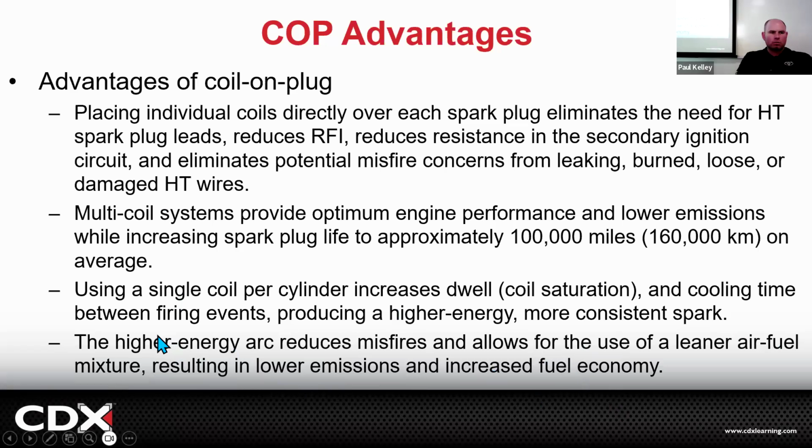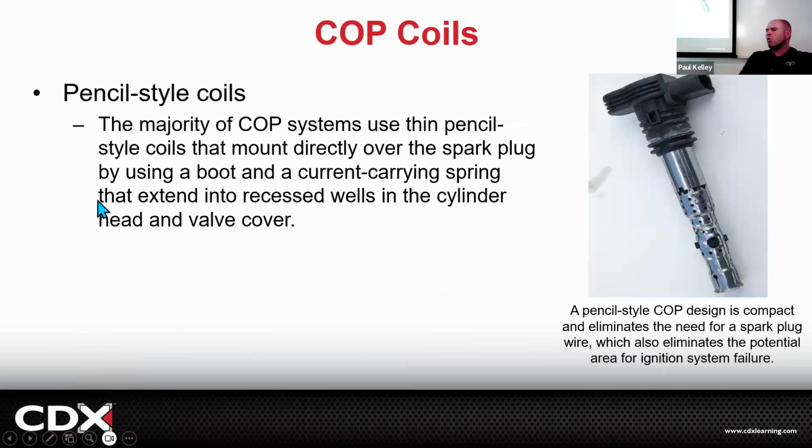As long as we deal with that NOx, which we do in a reduction catalyst, we can run lean and have low emissions, better fuel economy, but you couldn't do that with the old system, okay? So trust me, the old system is not going to come back. This one was improved in a lot of ways, except for initial cost to the customer.